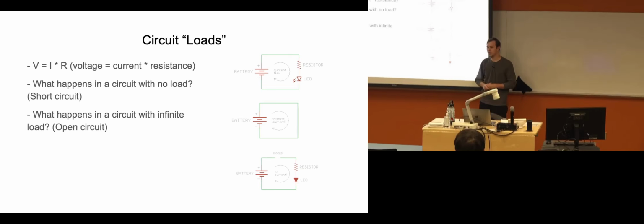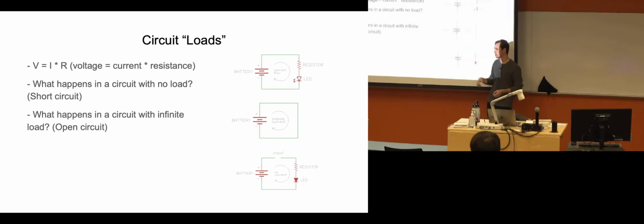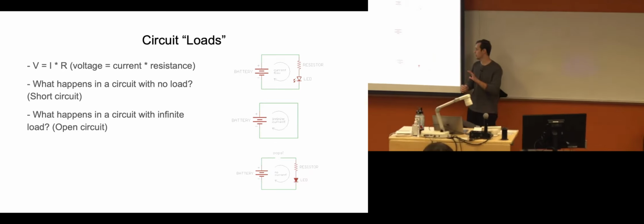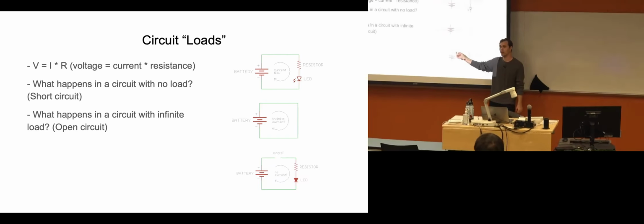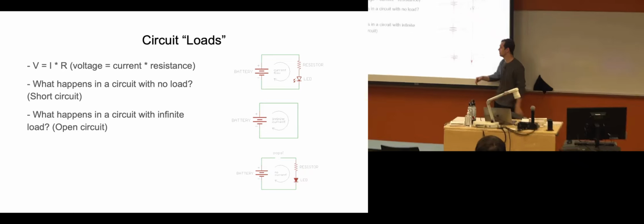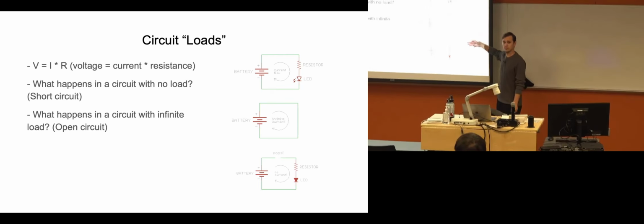I know not all of you have done lab 3, but for lab 3, when you make your MMIO and you do the read port with the tri-state buffer, and we talk about a high impedance mode, this is high impedance, right? There is no way for current to flow through here because it's disconnected. So when we say in the tri-state buffer, in the high impedance mode, you can think of that part of the circuit as disconnected. It's the same idea. It is physically disconnecting the wires, causing it not to influence the rest of the system. Do these three make sense? Is this intuitive? OK.